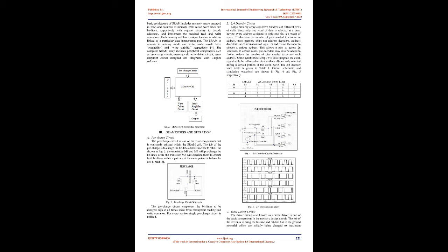2. SRAM and its peripherals. To get the required frequency of operation, efficient peripherals have to be designed. Since the memory core trades performance and reliability for diminished area, memory design depends heavily on the peripheral hardware to recover both speed and electrical integrity. Fig 2 shows memory cell with monolithic peripheral connectivity.